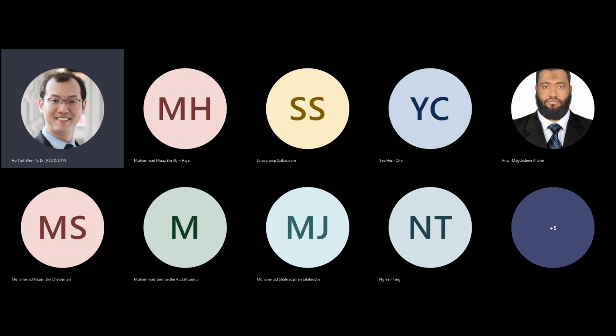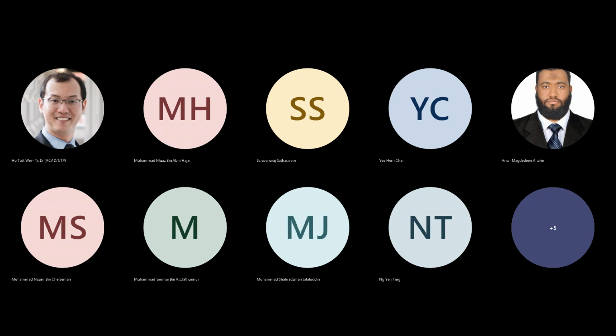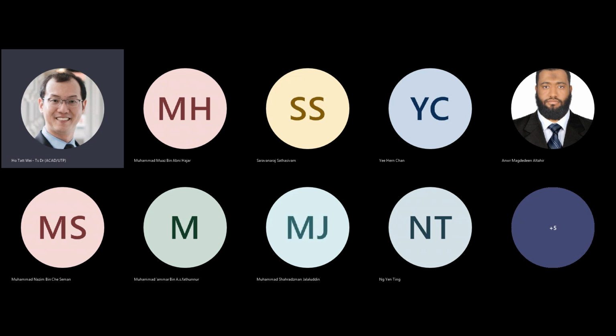our basic building blocks. And the first step is we are actually approximating these logic gates as a digital switch. Okay, so this is a symbol of a switch. And in particular, this digital switch is a voltage controlled switch, right? And this is called CMOS, or complementary metal oxide semiconductor technology, because you actually would build the digital logic from a pair of complementary gates, a pair of complementary transistors.